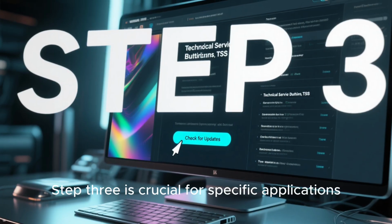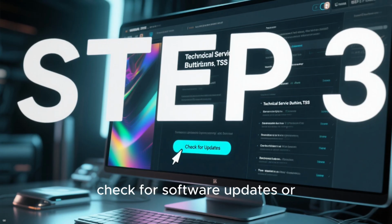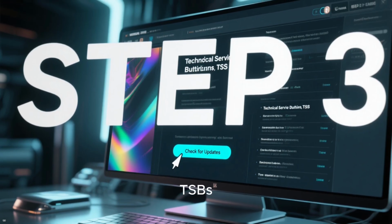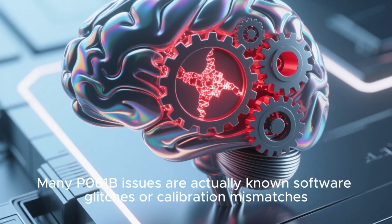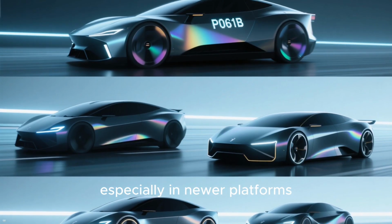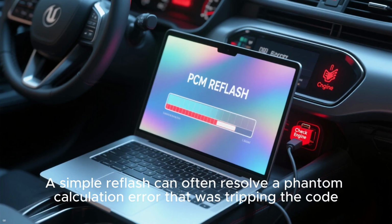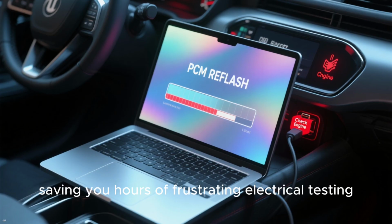Step 3 is crucial for specific applications. Check for software updates or technical service bulletins, TSBs. Many P061B issues are actually known software glitches or calibration mismatches, especially in newer platforms. A simple reflash can often resolve a phantom calculation error that was tripping the code, saving you hours of frustrating electrical testing.